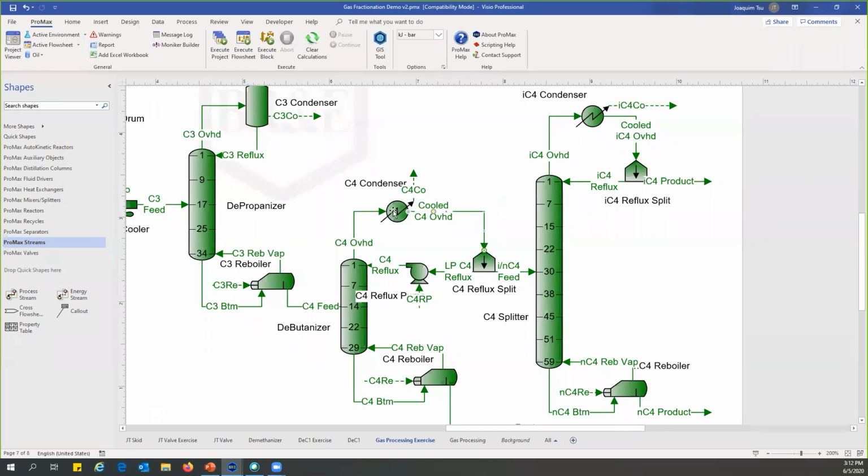Well, if it is fixed as saturated, we no longer have control over what temperature we have here. Therefore, we cannot link the control of the temperature here to this. Because if it's forced to be saturated, we already know the pressure here. So we're not able to change the temperature at all because it has a certain composition. It will have a certain pressure and a certain temperature as a result. So this is one of the simulation tricks which allows us to extend control of what we specify here onto this. That's one of the cute ways we can go about specifying.